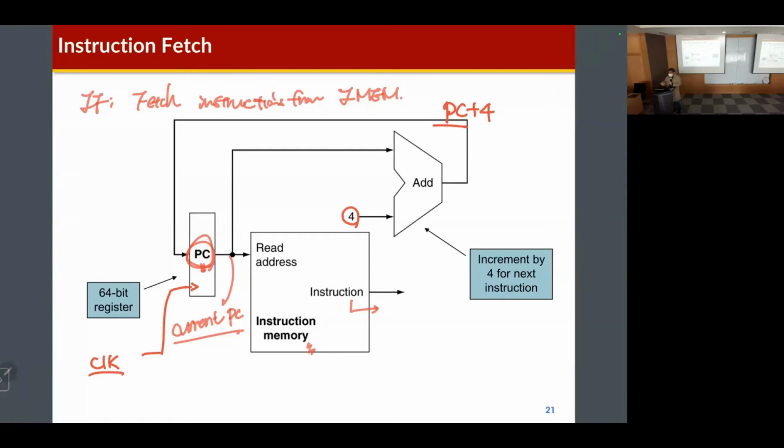So this is the single cycle processor. The definition of the single cycle processor is that it can execute a single instruction every cycle, which means we need to read an instruction every cycle, so we need to generate the program counter value for every cycle.